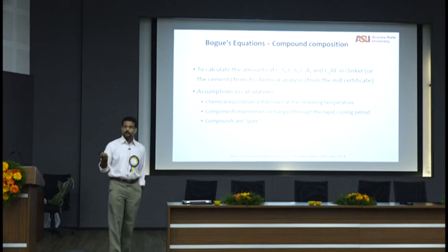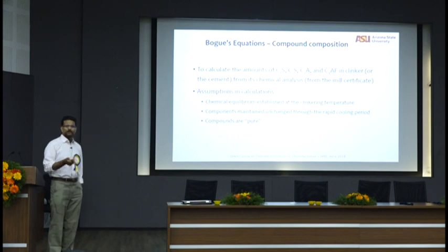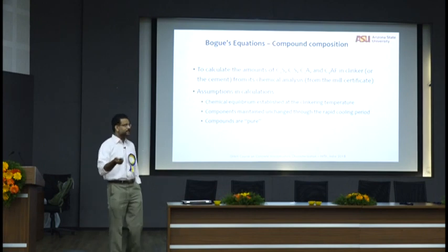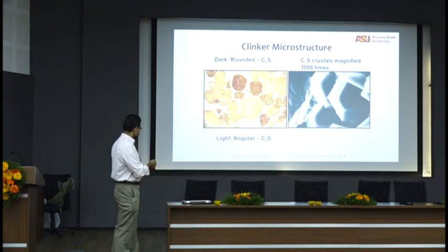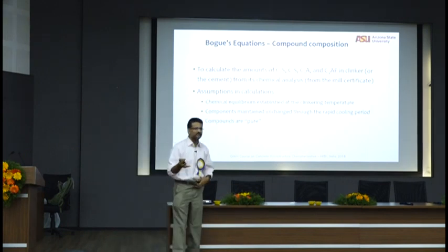Bogue's equations, all of you know Bogue's equations? Actually, I would recommend you not to study these equations, and not to use them. They're generally wrong. For the kinds of cements that we make now, Bogue's equations give, if you look at Bogue's equation, I didn't put the whole thing, they give you 2 different equations for 2 different C3A contents.